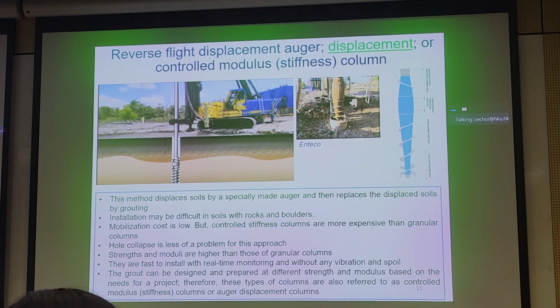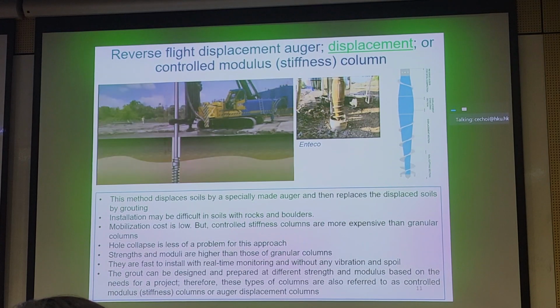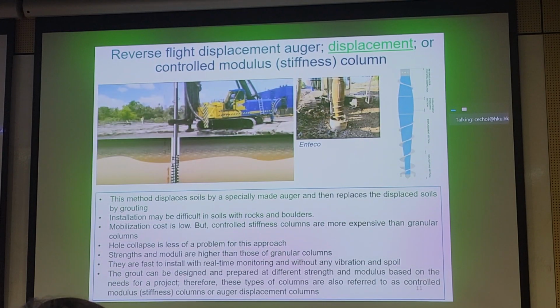When the drill is penetrated to the specific tip elevation or depth into the bearing stratum, advancement of tooling is ceased. At this point of the installation process, the drill stem now begins to serve a second purpose, which is that of a trimming pipe used for concrete placement.